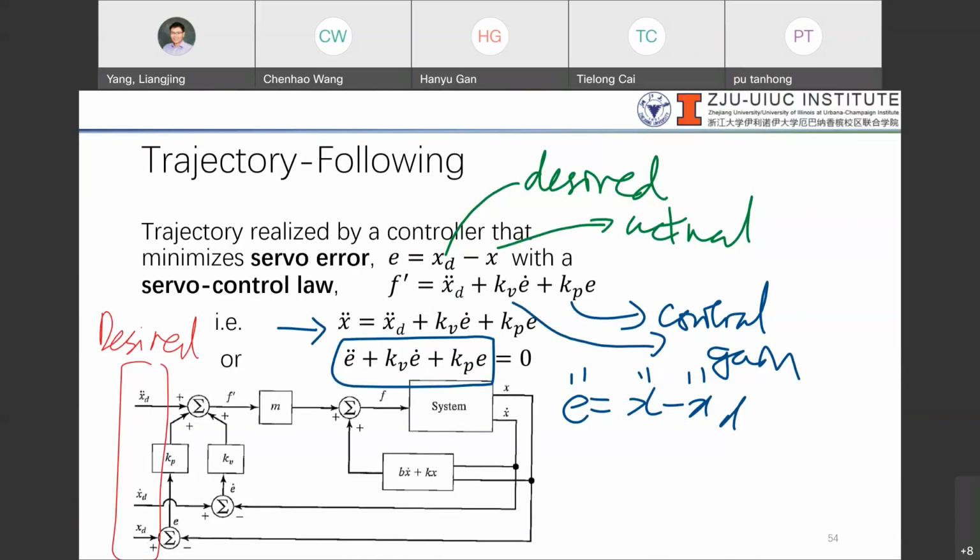That is your displacement, speed, and acceleration. So we can now specify a desired so-called trajectory, and having that trajectory pass into our system, the controller will come up with the right input to send into our system eventually. But this, of course, will be fine if we are doing trajectory tracking without disturbance.